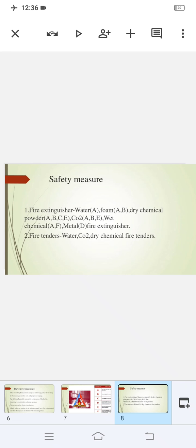Some sprinkler kind of system is also there. What is a sprinkler system? It is an automatic sprinkler system, a device for discharging water automatically on a fire. It will either extinguish the fire or hold it in check. So you will get some time to prevent it, and hence an independent sprinkler system with underground fire means for supplying water should be installed. When the heat from the fire reaches the point where the soft soldered compound melts, it automatically sprinkles water.